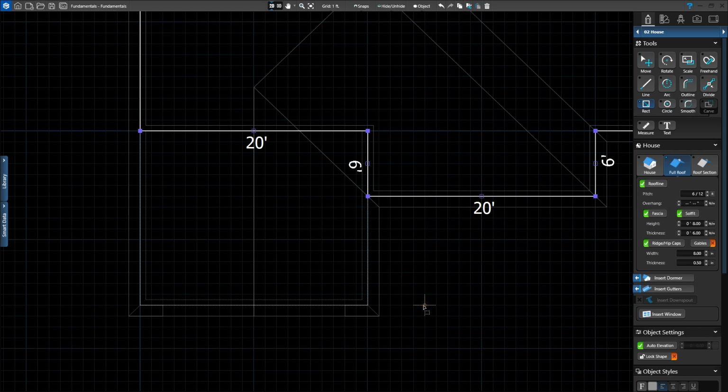If you were going to make a rectangle, you would left click and drag your tool to the desired dimensions and left click to complete your shape. When you're drawing a square, there's a prompt on your keyboard that you can activate to tell the rectangle tool to make all 4 sides even, and that's what we're going to use here.